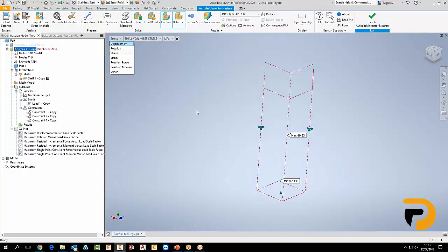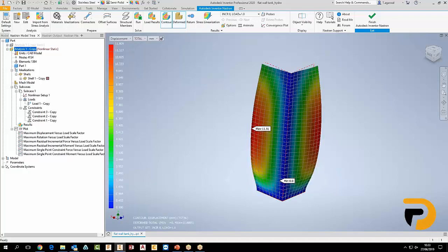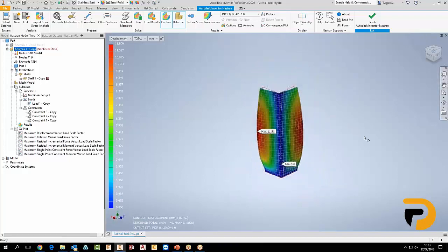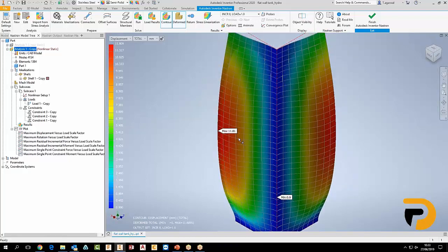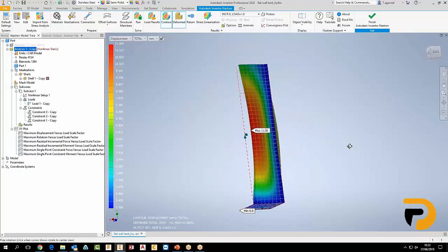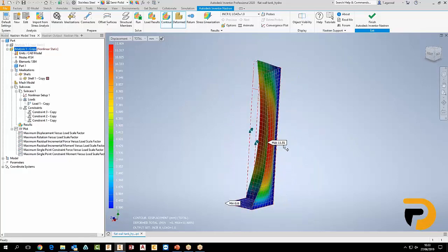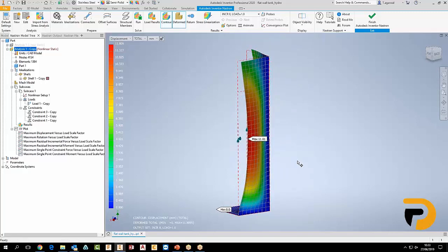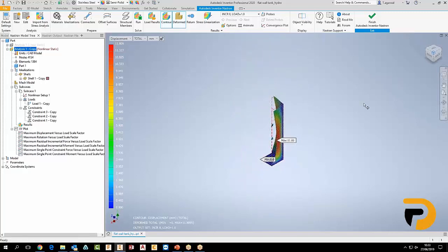Now, looking at the nonlinear displacements. Do you remember the value from the linear static stress analysis? That was 18.04, and now with the nonlinear one, it's showing me that this deflection is much less. That is 11.81 m. So that's something about the accuracy of the result. So it almost changed by 60% or like 30%.